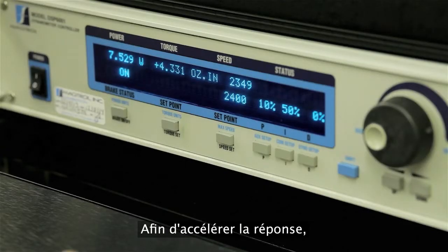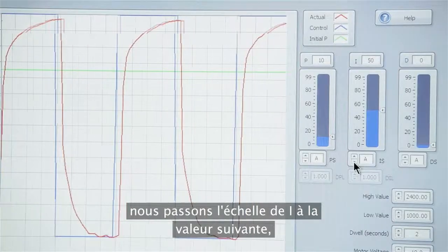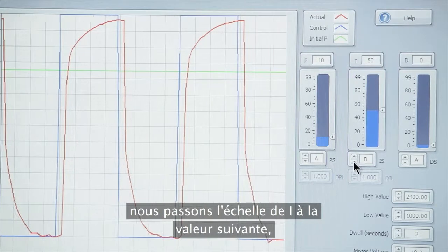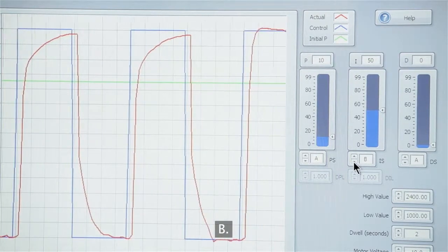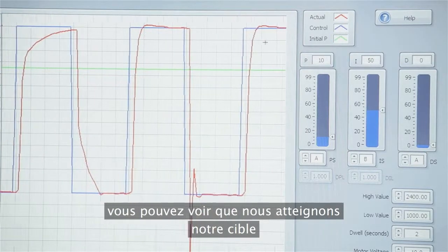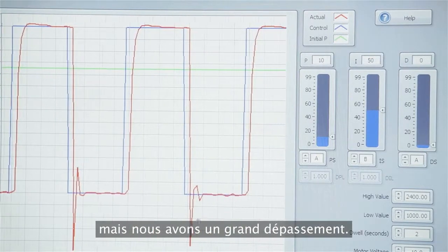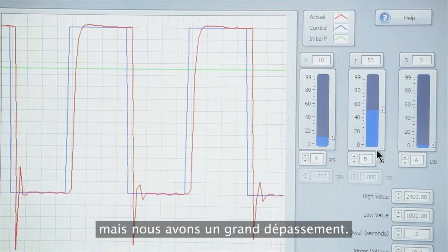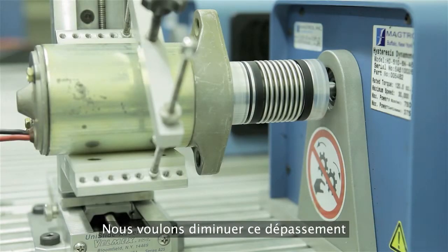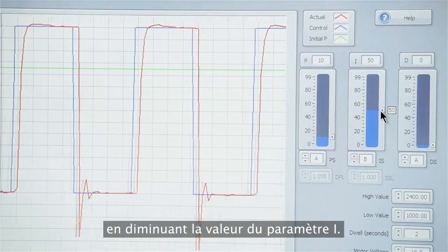So in order to speed up that response, we'll change our I scale to the next value, B. Now you can see that we are getting to our target much faster, but we have a fairly large amount of overshoot. So we want to bring that overshoot down some by adjusting the I term to a lower value.